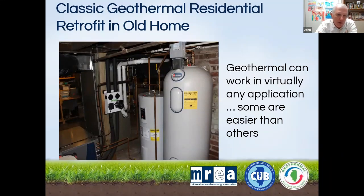You see the unit down in the lower left with the silver and blue. That's a WaterFurnace unit. I can recognize it. And it's connected. It's much like a furnace, except it's got piping connected to it, right? And you see the white box with the black circles just left of center. That's the flow center. That's the pumping system. In other words, 2 pipes coming from the outside, one coming in, one going out, and that's pumping that fluid over for the geothermal unit to take energy from that fluid and then sending it back on a return trip through the closed loop into the earth. And then lastly, you see the 2 water heaters over on the right-hand side of the picture.